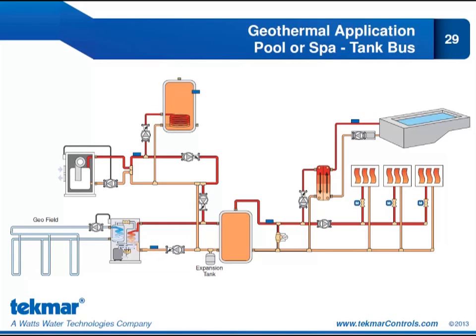From a control perspective, again, since I have at this point 4 zones off my tank bus, I could just use those 4 onboard zones on the 406, and I could connect 3 heat-only thermostats this time, so I wouldn't use the thermostat 557. I would use instead a heat-only thermostat like the 552, and I could use one of those onboard zones for my set point control 161 or 162.